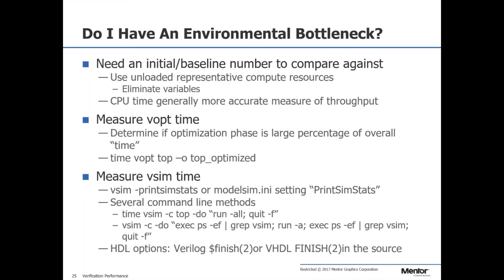Next begs the question, how do I know I'm getting the fastest simulation I can? Where is all of my simulation time going? That is where we have something that allows you to do a profile of your design. The first thing you need to do is some baselining. You need to figure out where am I, and how can I improve?